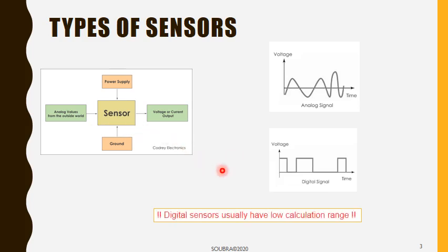This is why if you're looking for more accuracy, it's better to get a sensor that spits out raw data, and then you're going to deal with the raw data inside your microcontroller using the proper ports that are connected to the ADC, and you can also use some reference voltages using the pin that we tackled early in this course, and of course I'm talking about the AREF pin.